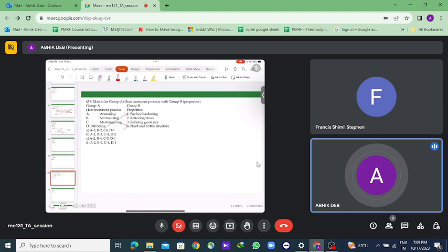It is because of this increase in the volume that we get the hard martensitic structure. It is a diffusionless transformation. Now, if we subject it to a high temperature for a significant duration of time, then the carbon from the BCT structure will start gradually diffusing out, which will result in the reduction of brittleness. So the process is tempering.